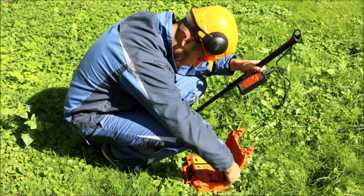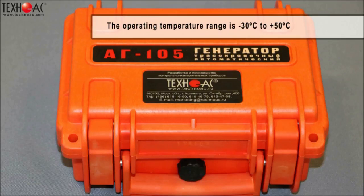AG105 is the best in class of the portable communication locating transmitters with low-powered autonomous power supply, in terms of qualitative characteristics, namely power, operating life, dimensions, and weight. Its weight is not more than 2 kilograms. The ingress protection rating of the casing is IP65, which completely precludes any ingress of dust or water jets when lidded. The operating temperature range is from -30 to +50 degrees Celsius, with the external battery or mains power